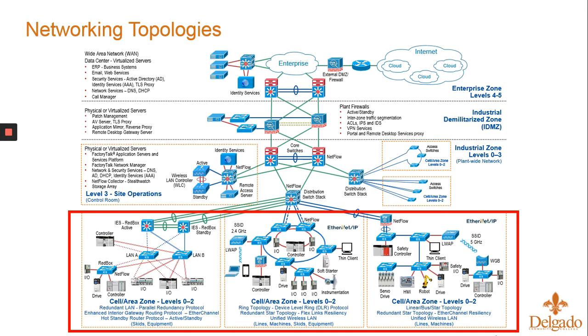At the same time, we don't want to give entrance into the enterprise system. We don't want people hacking into our corporate IT side and stealing our Coca-Cola secret formula or personnel data. So the IDMZ is a buffer zone to prevent rogue access between the layers.